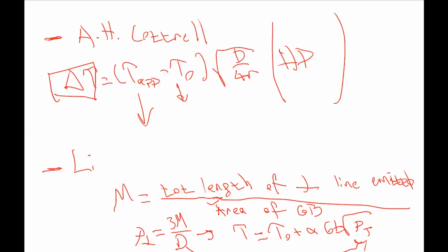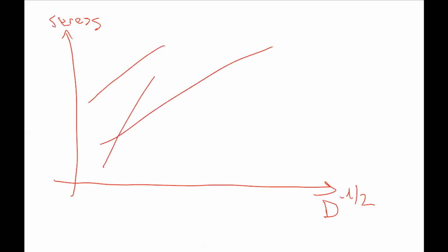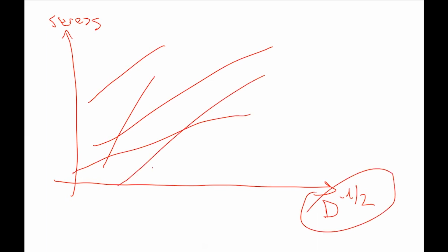Once we decrease the grain size, let me just draw stress versus d to the minus 1/2. We will see for different materials, different responses, but stress is always linearly proportional with 1/square root of d.